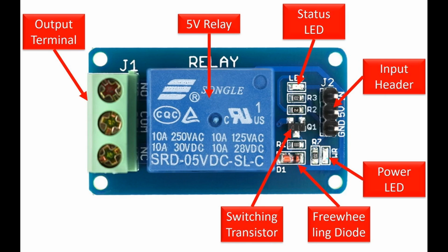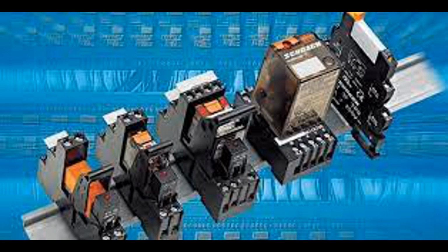a safe tolerance range. The differential relay measures this and remains inactive. Fault detection. If a fault occurs within the protected equipment, such as a short circuit or insulation breakdown, the currents at the two ends will no longer match. Differential current. The relay calculates the difference, or differential current, between the two measured currents. If this differential current exceeds the preset threshold, the relay activates.